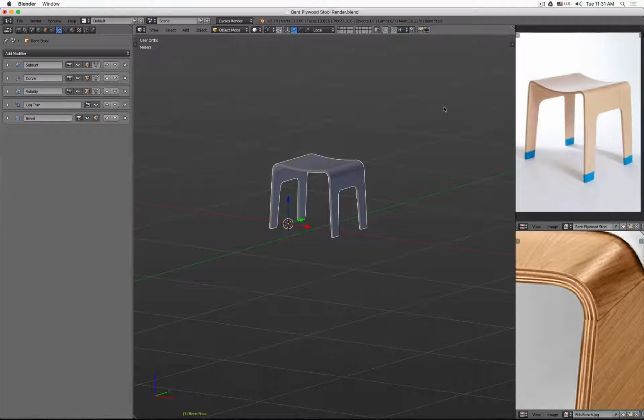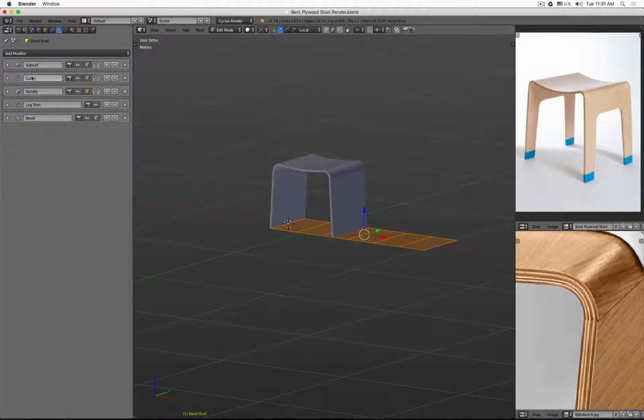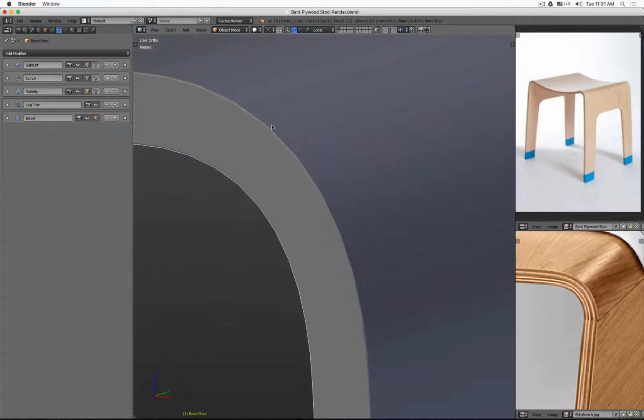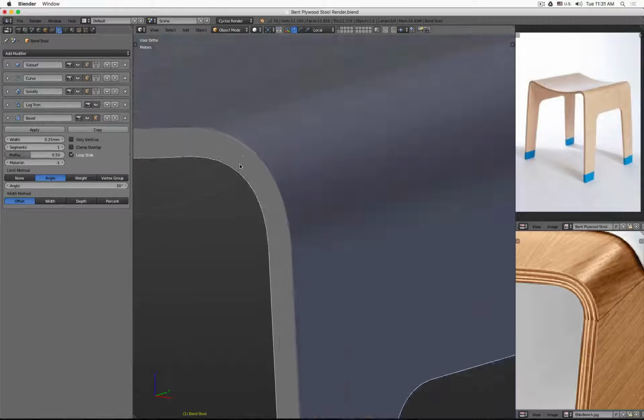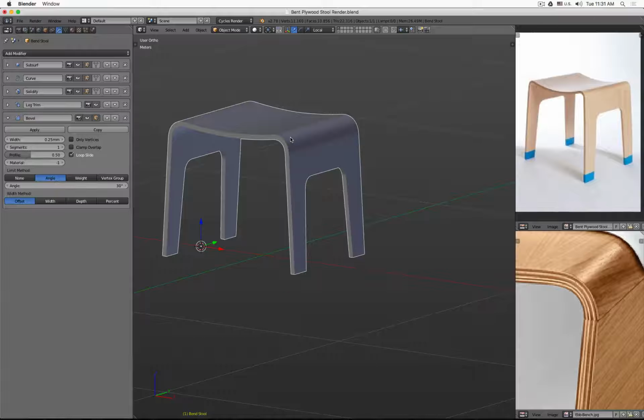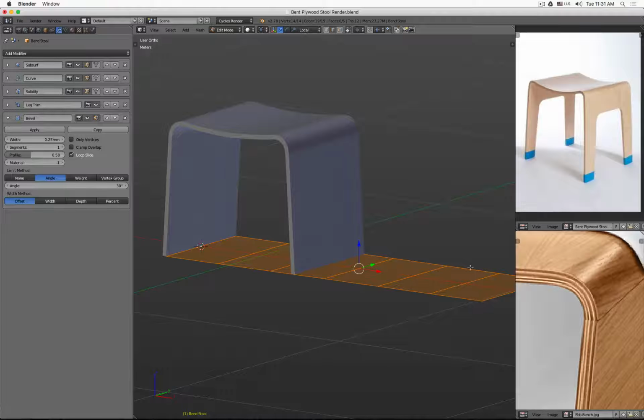So in Blender, the way we created this design was by using a flat sheet. Then we add geometry details, we bend it, we give it a thickness, and then we cut, for example, the leg out, and then at the end we decided to round the edges a little bit. And I use a very basic chamfer, just a bevel with a setting of 1. The problem there is, while I have now a three-dimensional object, when I go into edit mode, I don't have faces at the sides I could select to map this texture onto.